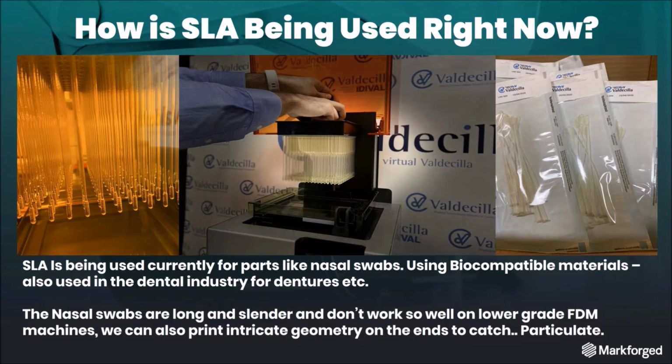has a home position. As you get further away from that home position, so further up in the Z axis, the accuracy of the part can start to deteriorate. So printing these long struts in the Z axis, you might see some warping on an FDM print, or just because the plastic is coming out of a nozzle, which usually has a diameter of about 0.4 millimeters, it's going to struggle with those very small amounts of detail.